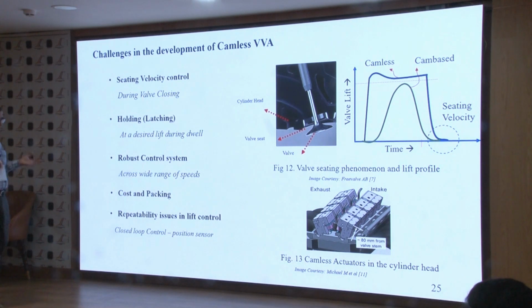In all these discussions, one question comes to mind: we are dealing with pressurized air, so where are we getting the pressurized air from? Another concept we are thinking about is that, as one of the authors has told, we are wasting a lot of energy in the exhaust gas, since very few SI engines are turbocharged. So can we utilize the turbocharged conditions and have a very small reservoir of compressed air on board itself?